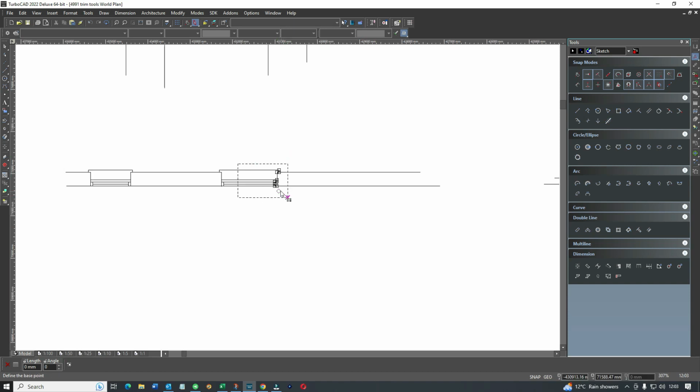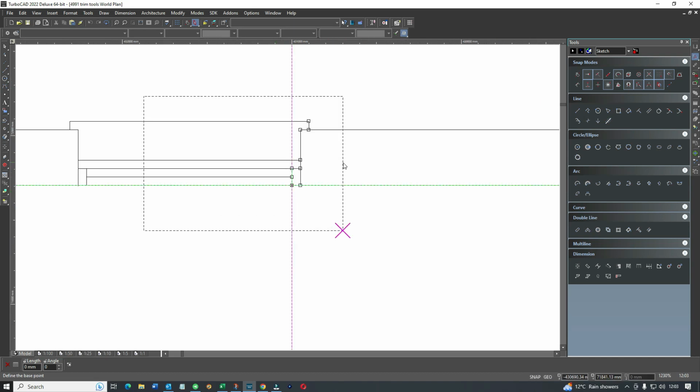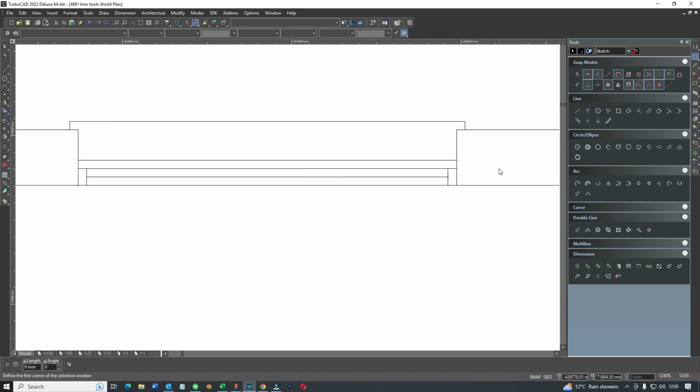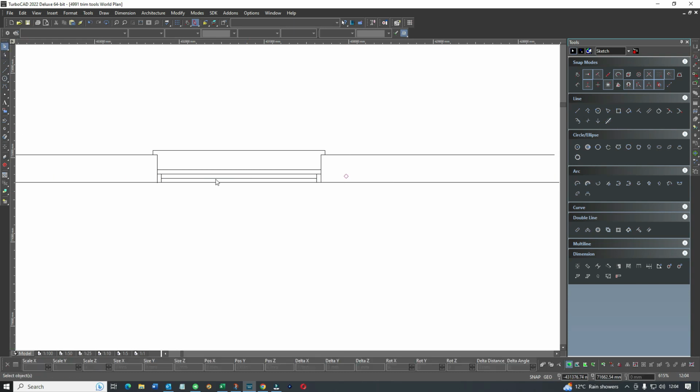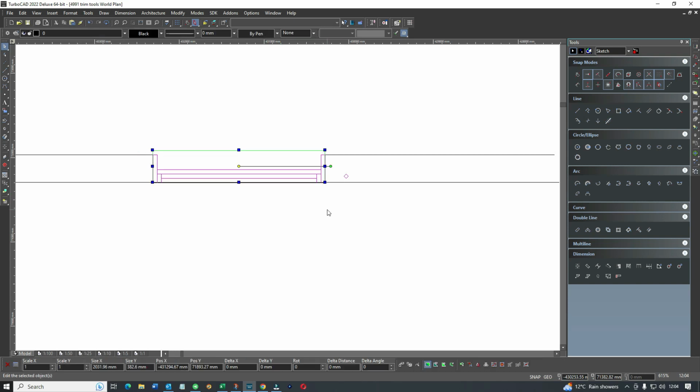So what I want you to do is get your drawings open. And incidentally, I can pull from anywhere. I'll show you another way of doing it. So I'm just going to select again. I'm going to reduce the window by tabbing. So now I'm at this position, tab, I'm down here, and I'm going to go minus 300 to reduce the window by 300. So you can do it by numbers, by measurements. If you know that the window, for example, is say 2.0, I could do that in half.